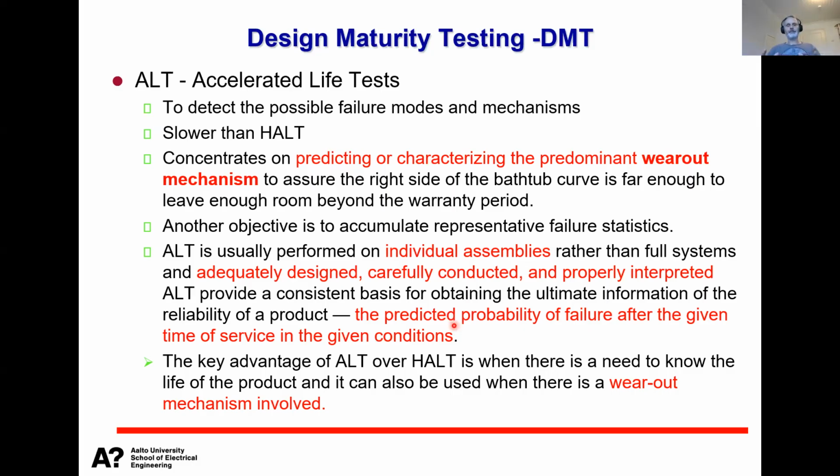But with ALT testing, you typically concentrate on individual parts and assemblies. So basically, you tear down the product and you test separately, let's say, the display with the stresses which are relevant to the display.